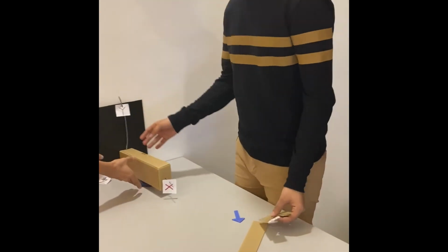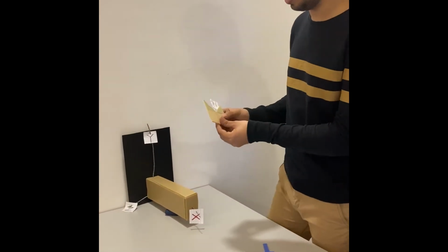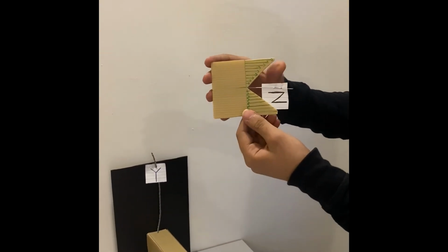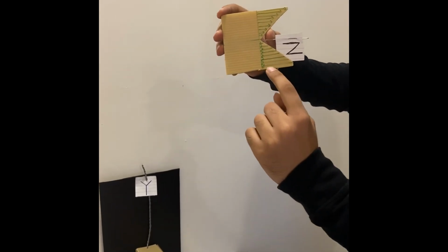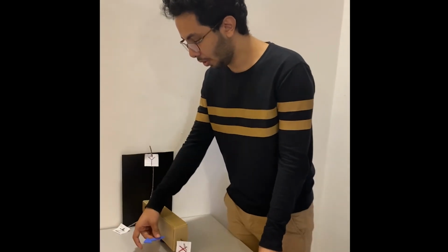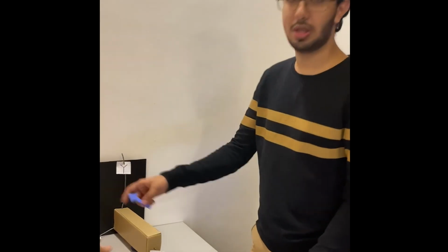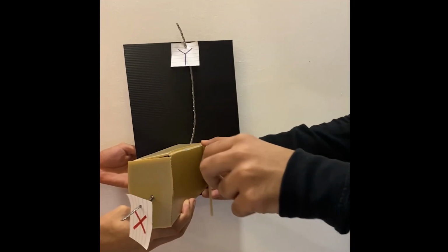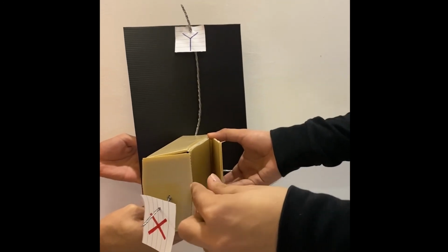And now after cutting the cross section, we will have a stress distribution due to the bending force. So this is our stress distribution acting in the z direction. Here we will have a tensile force acting to the outside, and a compressive force acting inside the beam. Now our second point load, which is the 2,000 Newton, will cause a deflection in the z direction. So this is our original plan of the beam, and because of the second load, it will cause a deflection at this distance.